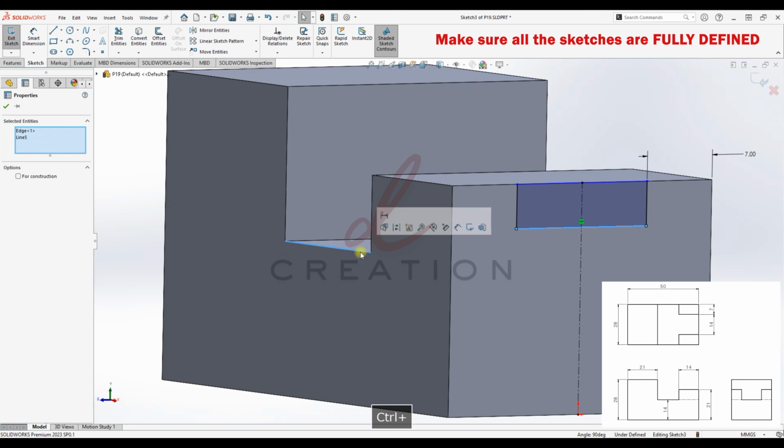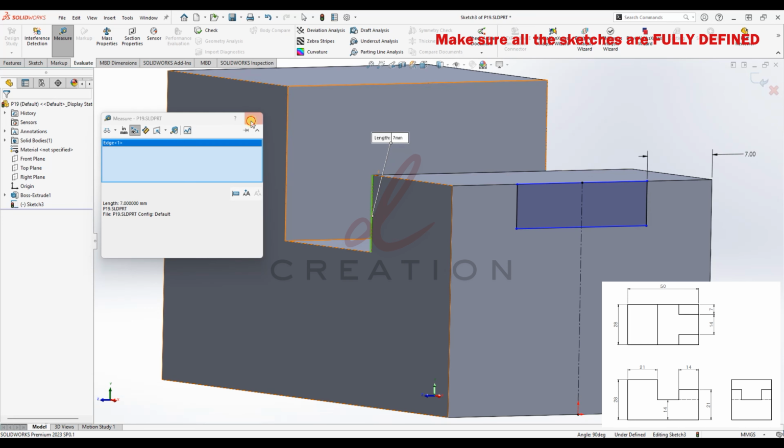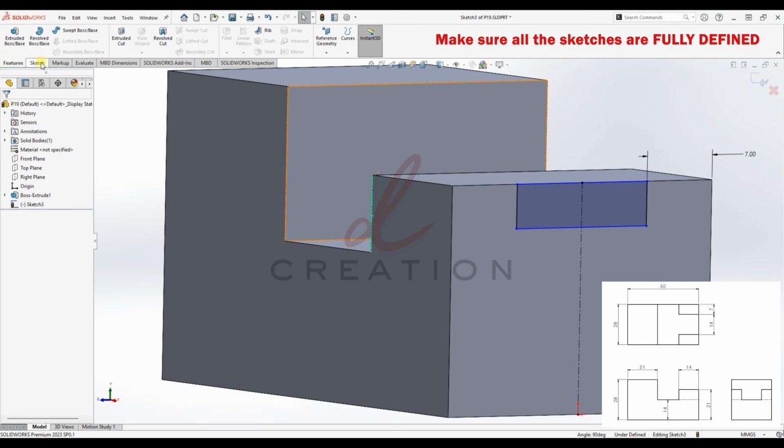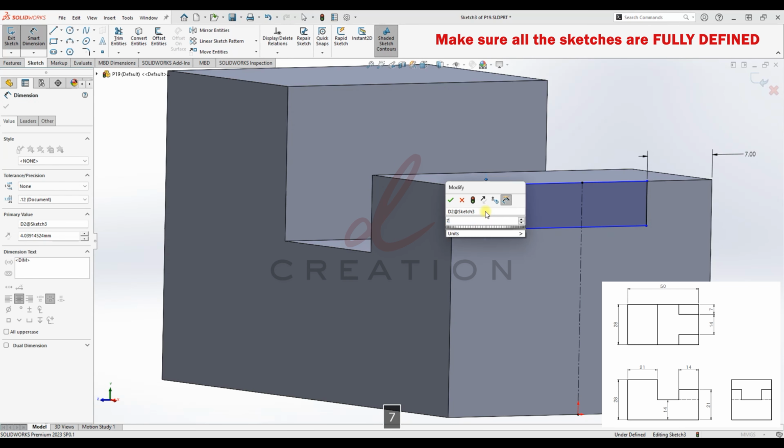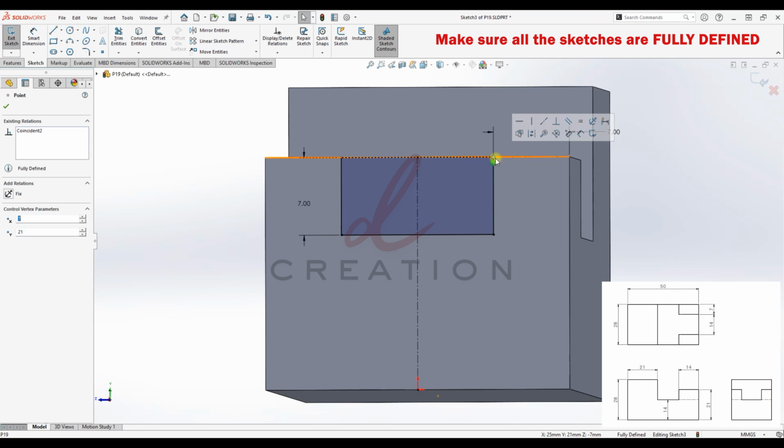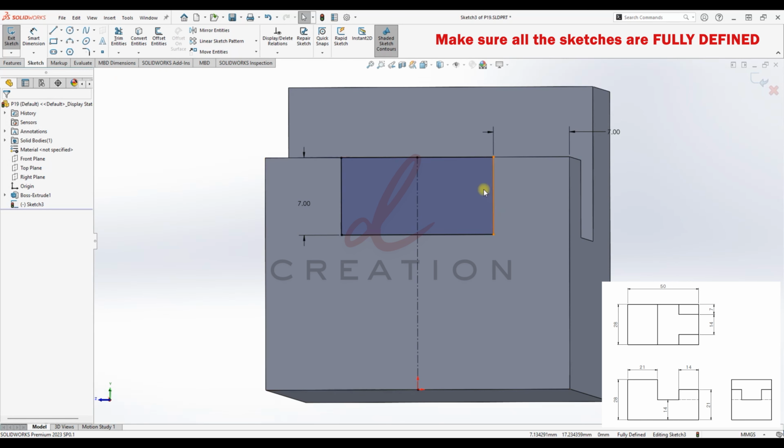The height of this line needs to be equivalent to this line, so I go to evaluate to measure the line. I just click on this edge, and it's 7 mm. So with smart dimension, the height will be 7. You can see now the problem here is this line does not coincide with this line. So make sure you bring the edges, drop down until you can see the line highlighted in orange. Click on that, and now your sketch is fully defined.